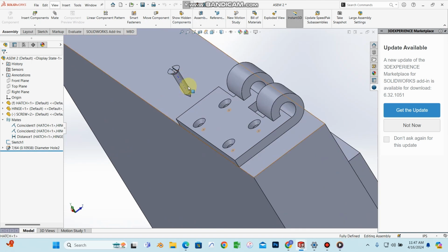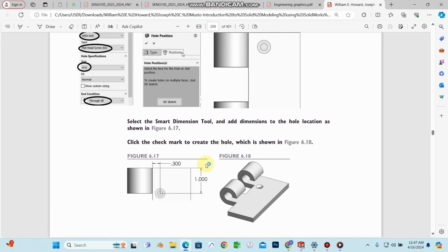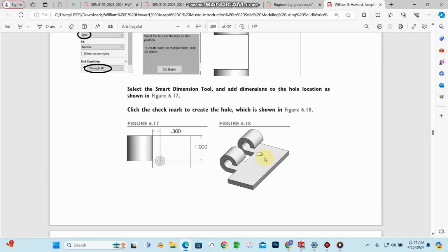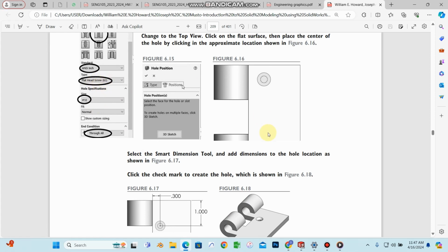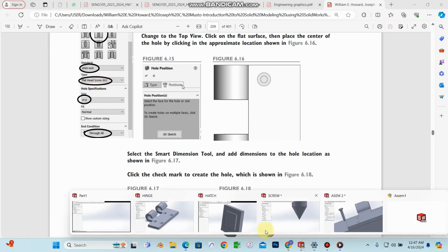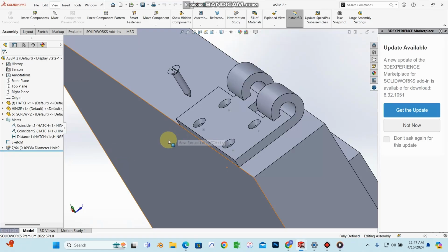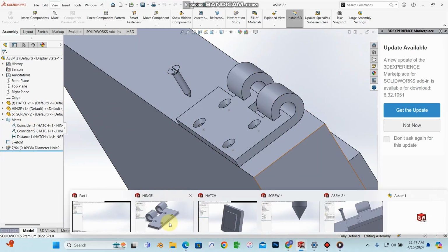You can realize that there was a break in the video. I made a mistake with the size of the, let me check. I made a mistake with one of the sizes. It was the size of the hole for the hinge. I didn't choose flat head screw 82. Mine was flat head screw 100. So the mate wasn't working. So let me show you what I did.